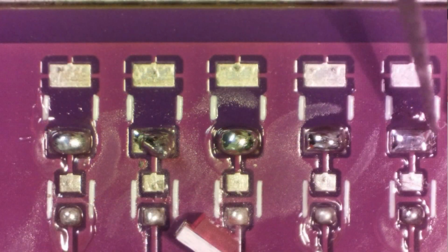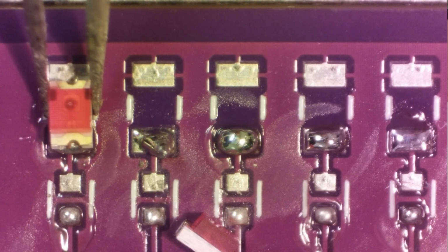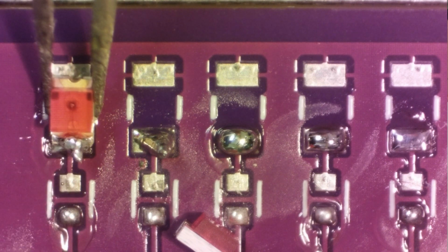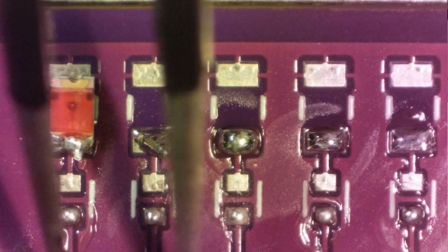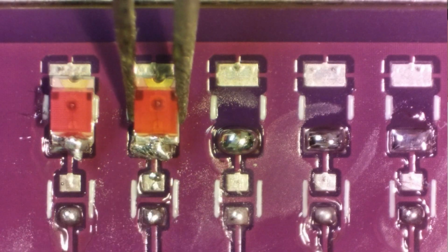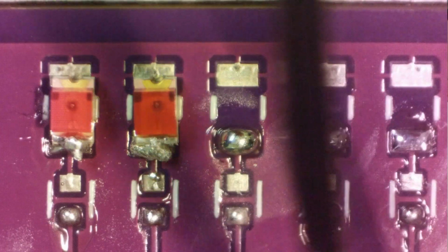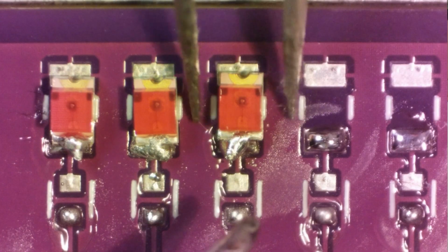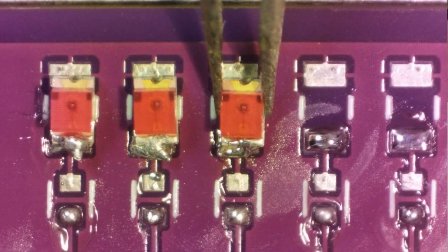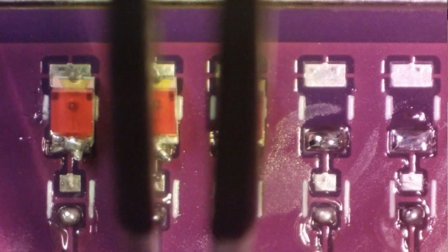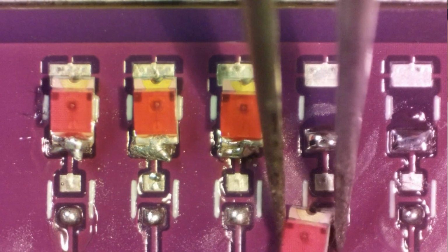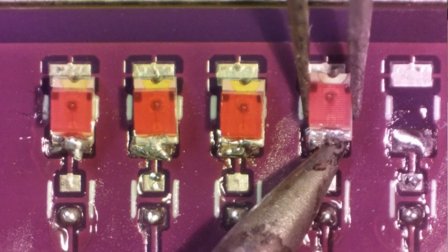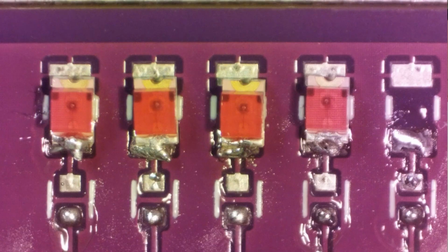All right, so this is what they look like. The little markings go to ground. We'll just tack them on, get them in the right orientation, tack them on, and then dump some flux and reflow everything nice. It looks like I'm getting a lot of solder lately for some reason. I cleaned my tip and it might not be tinned well enough. We'll see what happens. Might have to switch to my other tip. So I better put them in order here. Okay, there's those tacked on.